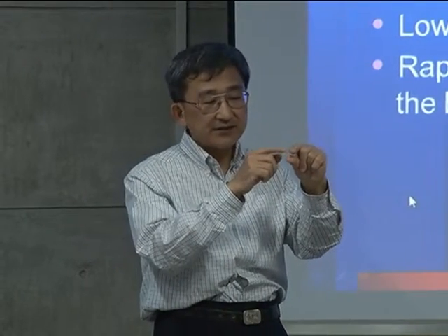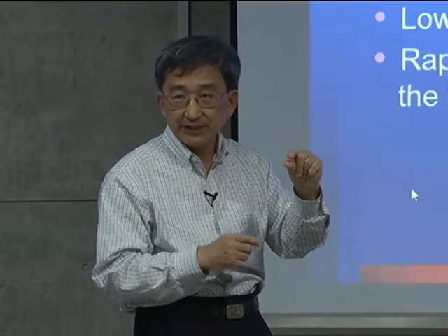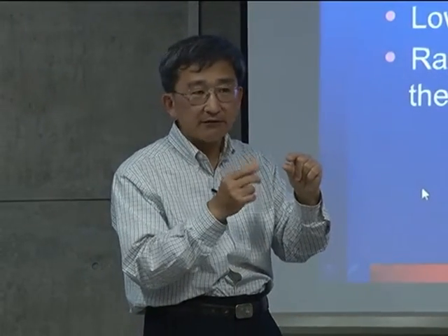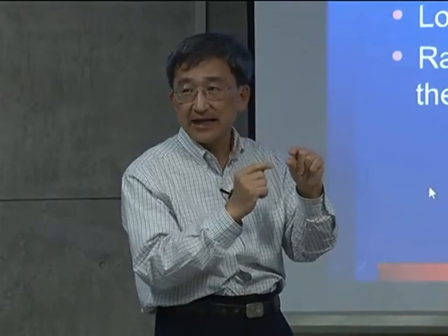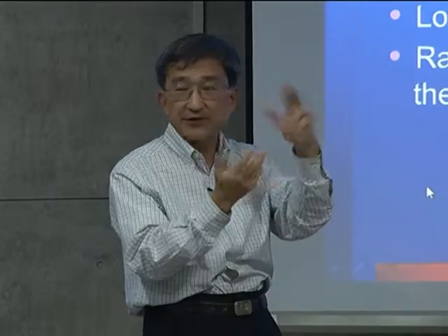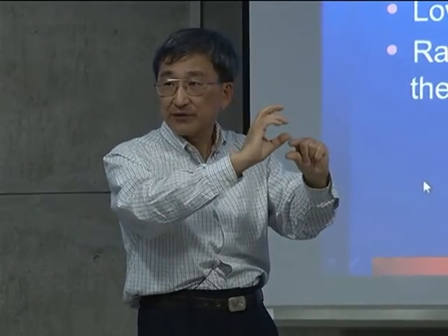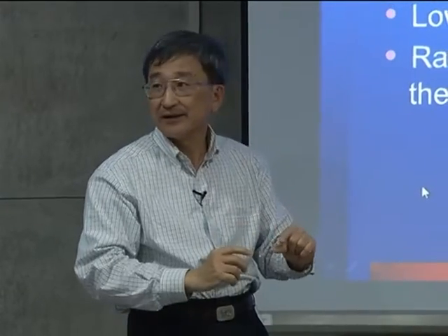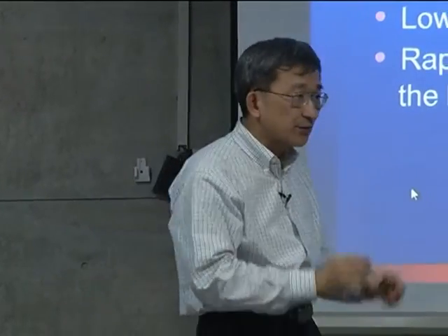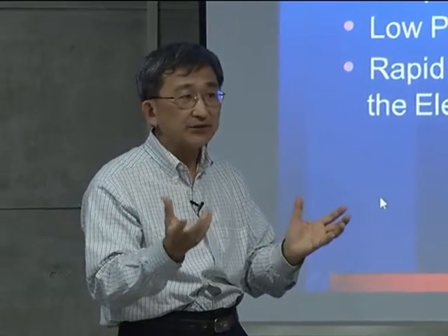If you reduce the spacing between electrodes, you don't really need a high voltage, because creating a corona depends on the electrical field, which is the voltage divided by the distance. So you reduce the distance, then the required voltage is proportionally reduced. So when you apply this to a micro device, you don't need to go to a high voltage.